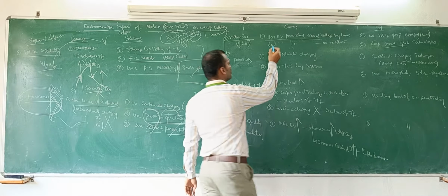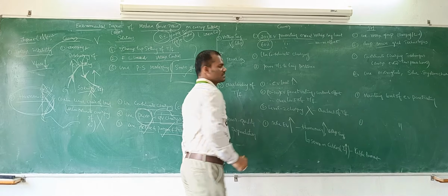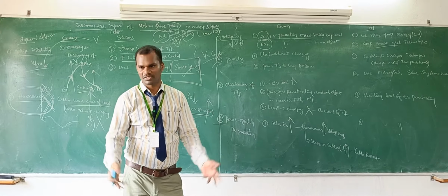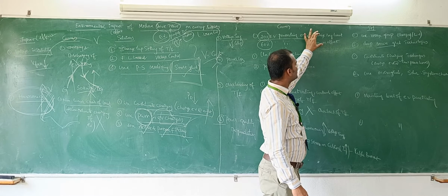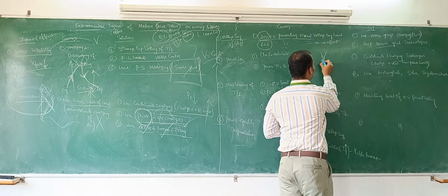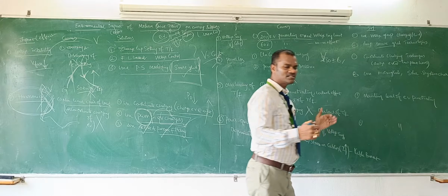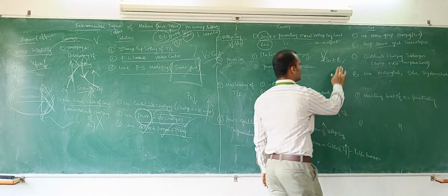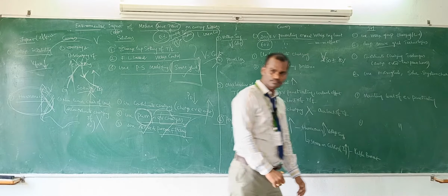If we increase it to 20% or even 60%, our system can withstand. But what will happen is they will increase the range of voltage sag limit. What is the voltage sag limit? 230 volts plus or minus 6%. When you increase more electric vehicles, this percentage tolerance has to be increased to 10%.